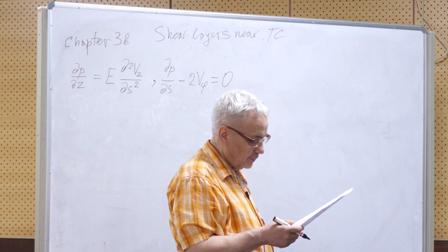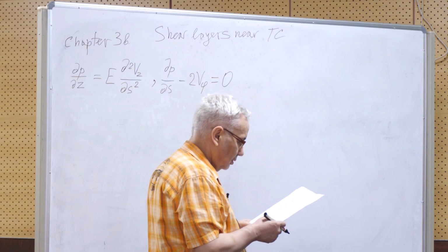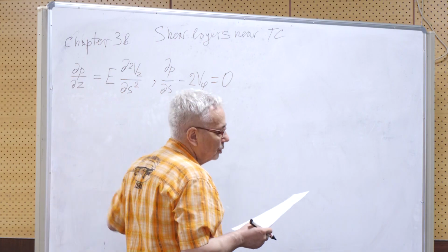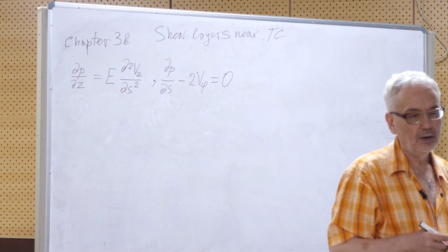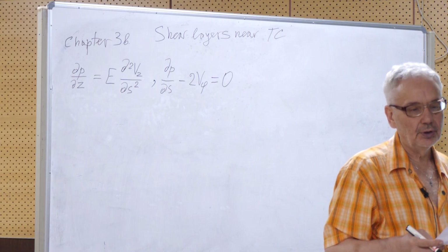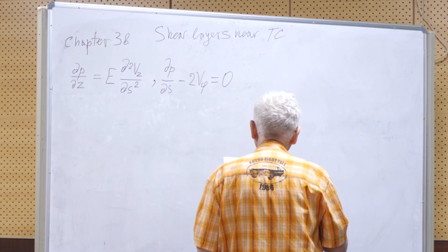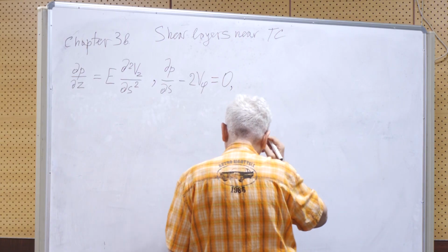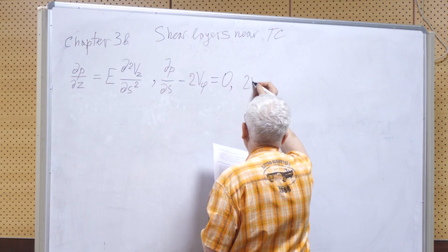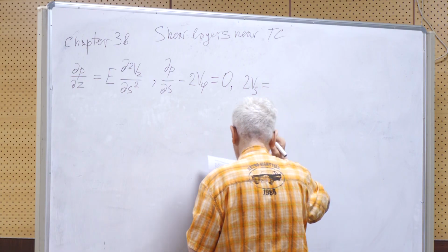Then if we consider the other component, the phi component, there is no such trick for that. For this phi component we have almost no pressure because, as I told you, we have almost no dependence on phi, and so the gradient of pressure is also zero. So in the next equation, in the phi direction, the pressure term disappears and we are left only with the Coriolis term, which is of course balanced by the viscosity term.